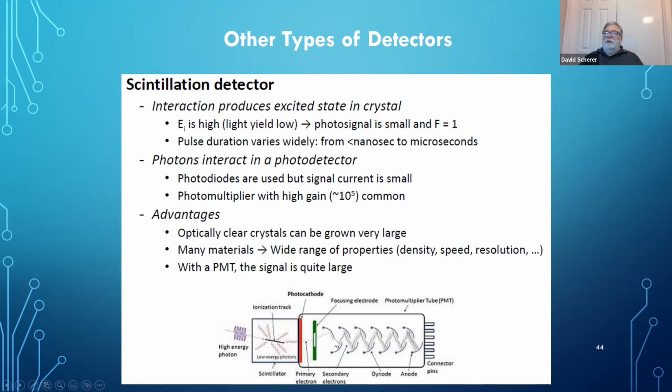In these photomultiplier tubes, there are stages that are called dynodes. There's a high voltage that attracts the electron. When one photoelectron interacts with a dynode, it will liberate more electrons, a few hundred or thousand. They're transferred to another similar dynode that's at a higher voltage. For each electron that reaches that point, the same amplification takes place, so it goes through several stages and the number of electrons multiplies each time.